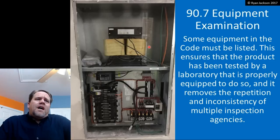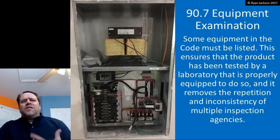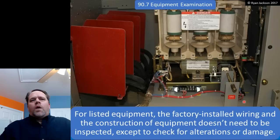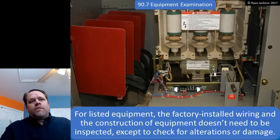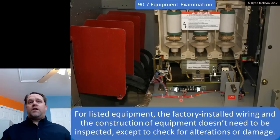Because it removes the requirement for individual inspectors to test it. Plus, I don't really have the capability of testing this transformer. That's something that has to be done by a laboratory. So some equipment has to be listed, and when it is, that means that I don't have to inspect it. For listed equipment, the factory installed wiring and the construction of the equipment does not need to be inspected, except to check for alterations or damage. I'm not going to get out my magnifying glass and start sizing these conductors and making, is that THHN or is that XHHW-2? I don't care. It's a listed piece of equipment. I'm not inspecting it. I don't have to inspect it. I just need to make sure that what?